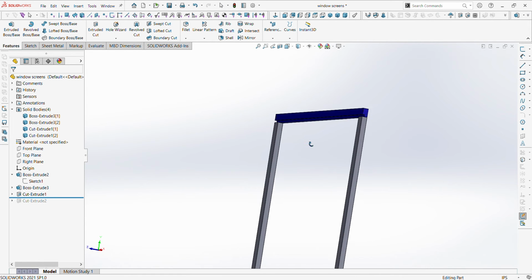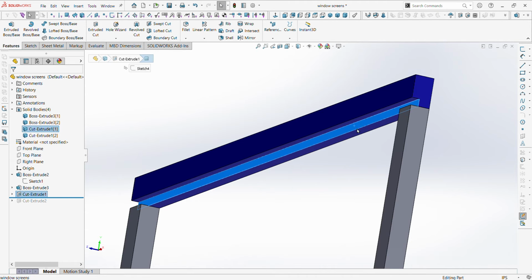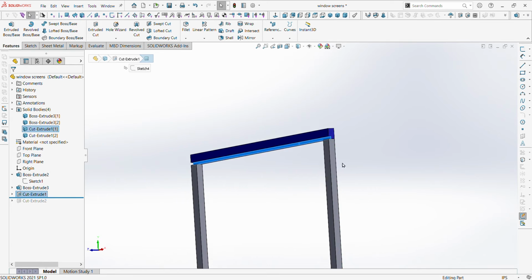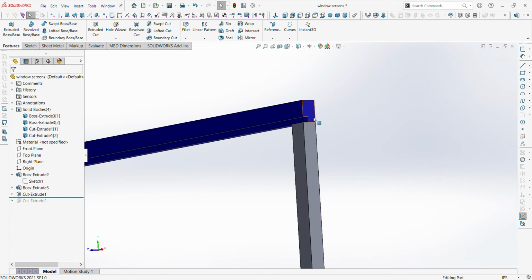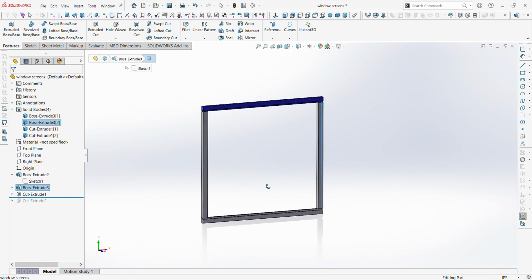Anyway, so this next sketch, I'm going to cut a groove on the side of the railing to accept where the screen goes. So the screen will get stapled on this surface here. And I have to run the stock on the table saw to rip out this dado notch. So when I create this stock, this profile, it has to have that feature in it.